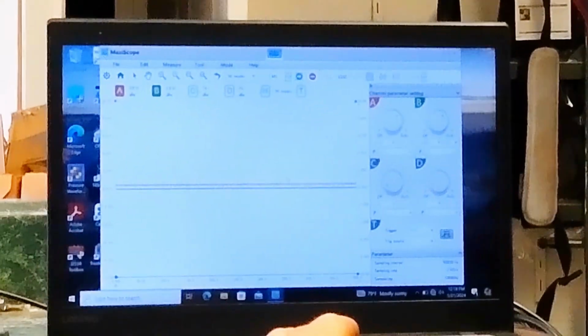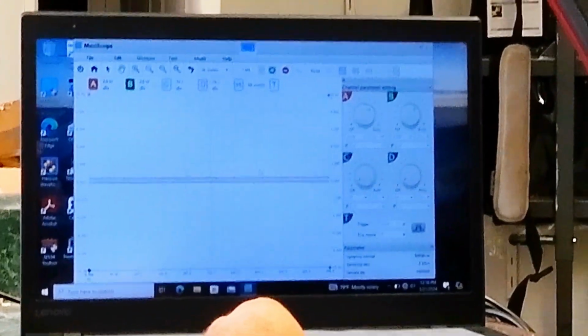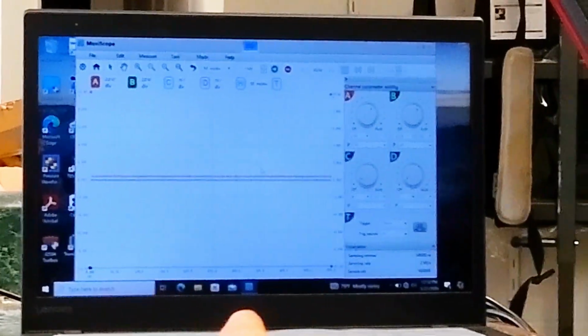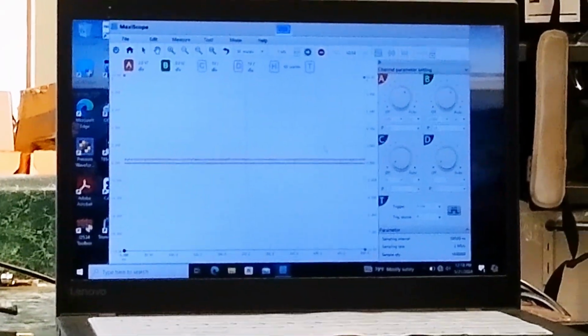Okay, so the only wire hooked to this is the network wire from the air conditioning HVAC module. You can see occasionally a little blip here. That is a 7 volt pulse that's coming from the air conditioning module.